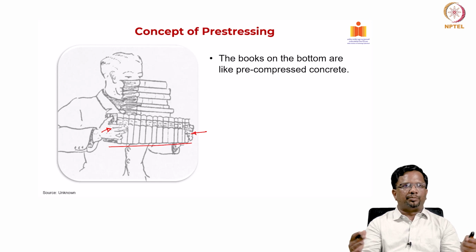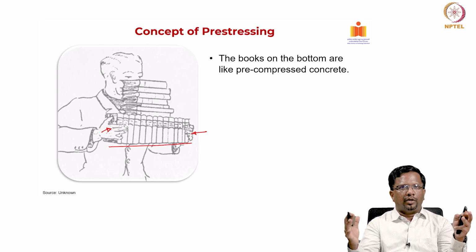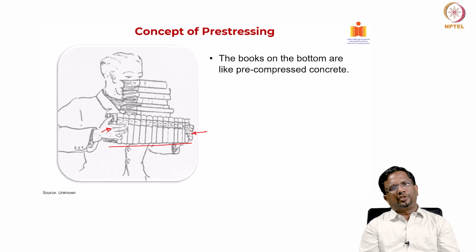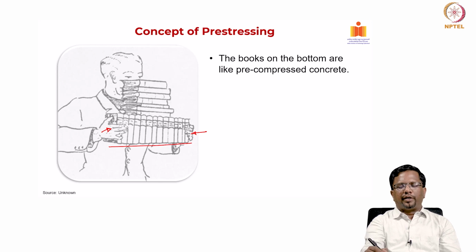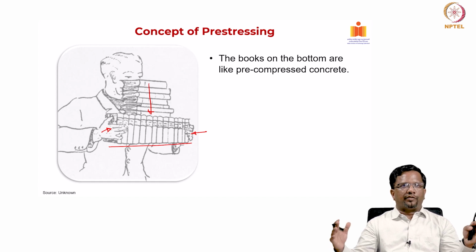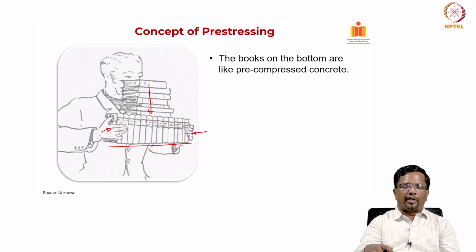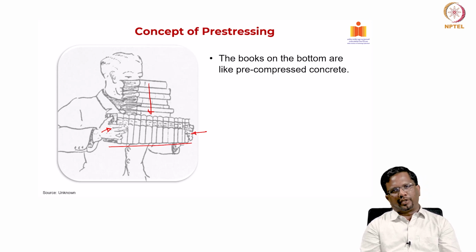If you do not have this pre-compression, the effect from squeezing these books, then it cannot really take this load, right. So, then the books will separate from each other, right. But if I squeeze this bottom stack of books, then I can apply load onto that. That is exactly what we do to concrete as well.